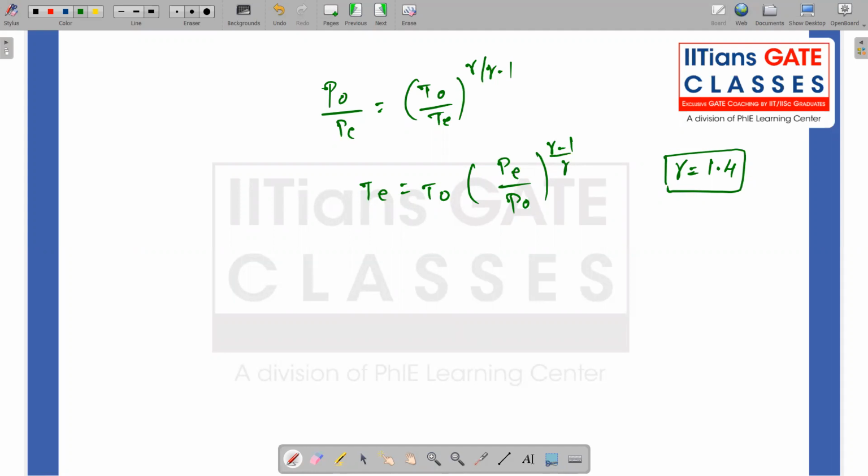1.4 is for air, but in the question they actually mentioned a CP of 1000 joules per kg Kelvin. I have not shown that here, but for CP close to 1000 joules per kg Kelvin, the gamma becomes 1.4 for air. So that is why I am choosing gamma to be 1.4. But remember that the value of gamma is usually given in your GATE scenarios, or at least they will give a way to calculate gamma, right?